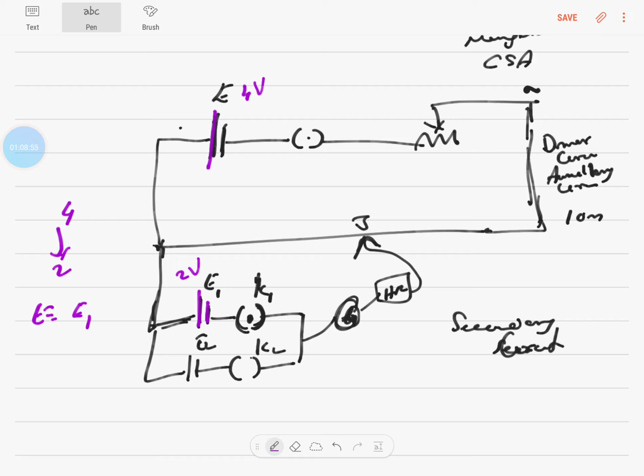Can you see? The potential drops from 4 volts to 2 volts. Therefore it's mandatory that the auxiliary or driver circuit voltage is always higher than the batteries in the secondary circuit, because the voltage has dropped down and become equal, so when there's no potential difference, no current will flow, and the galvanometer will show zero deflection for one particular length.